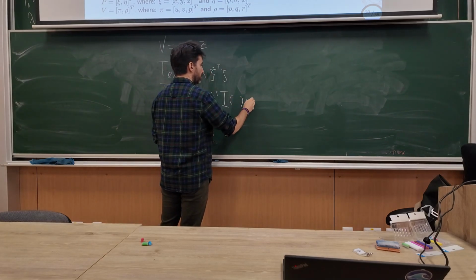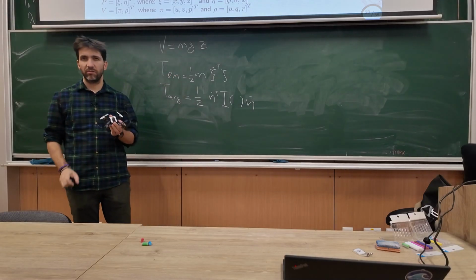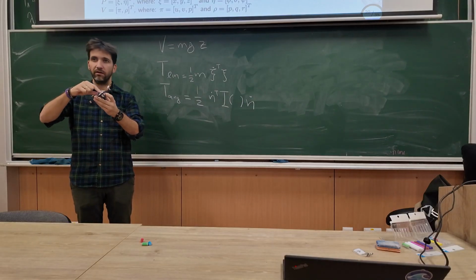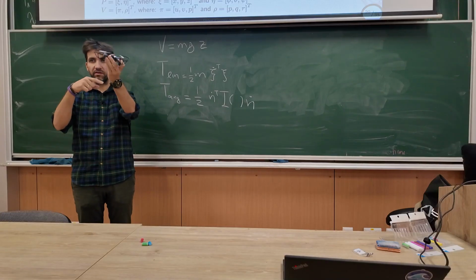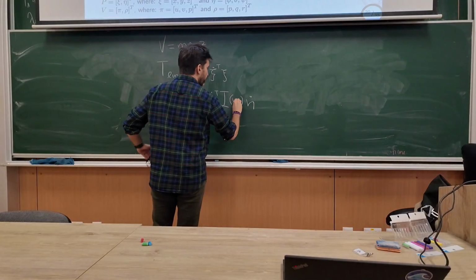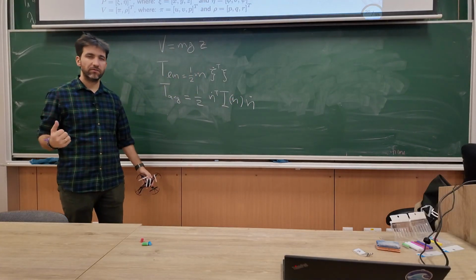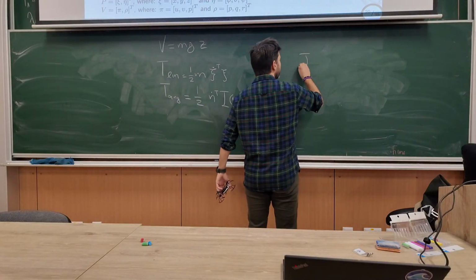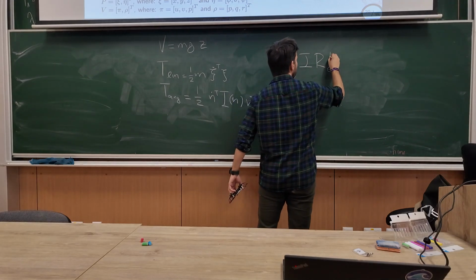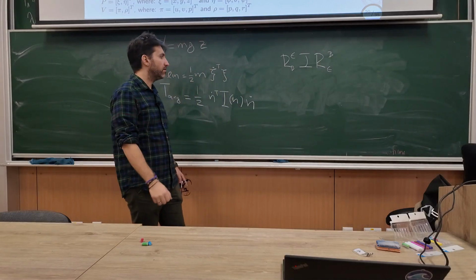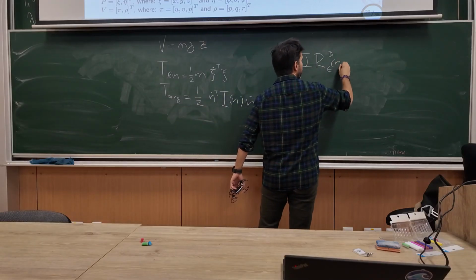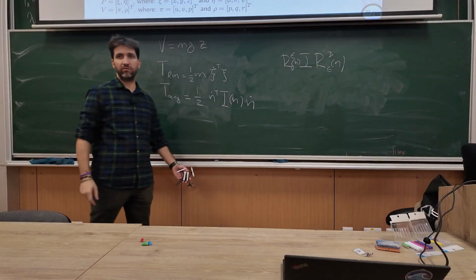And I'll tell you one thing here. The moments of inertia, if you remember, was some matrix that was expressed on the frame of the link. In this case, it is expressed on the frame of the body of the robot, but since we describe everything in the Earth frame, I have to translate this to the Earth frame. If you remember how we did this for robot arms, it was with the transformation matrices. So this was B to E, and this would be E to B. That's how this thing is basically that thing, and this is a function of eta. That's why this thing will be a function of eta.